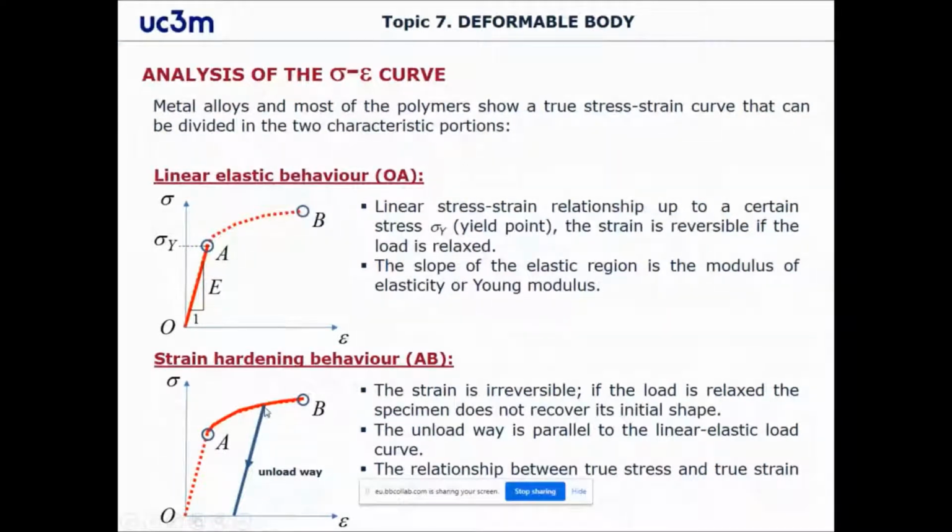the material, first of all, is going to deform. Of course, it's going to deform. It's going to lose certain stiffness. You can see that the slope is way smaller. And what is important here is that once I remove this load, the material is not going to return to its initial position, but is going to unload and is going to end at a certain strain, right? This is called the remaining plastic strain, and that's the main reason why we lose a certain amount of energy in this kind of process.